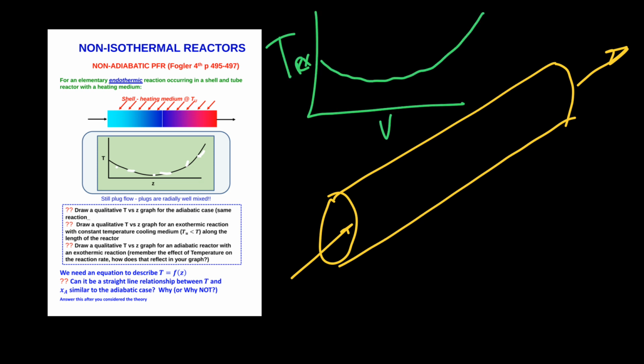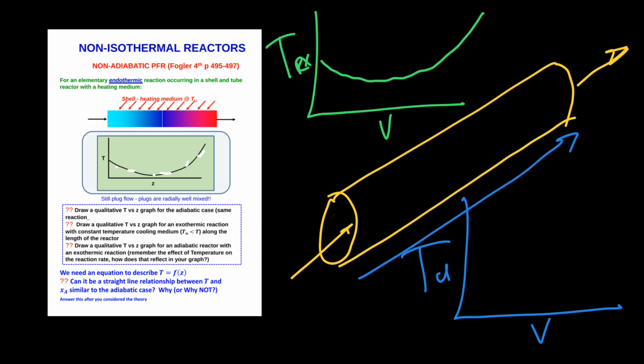So if I consider the other variables that will be responsible for that rate of heat transfer, it will also be a function of how the utility's temperature changes along the volume or whatever independent variable in my reactor. So I may start with a warm utility, but it's going to cool down because of heat transfer along the length of my reactor. Other variables, of course, is the amount of heat transfer area that is available as I've got this incremental slice that I'm now going to evaluate.